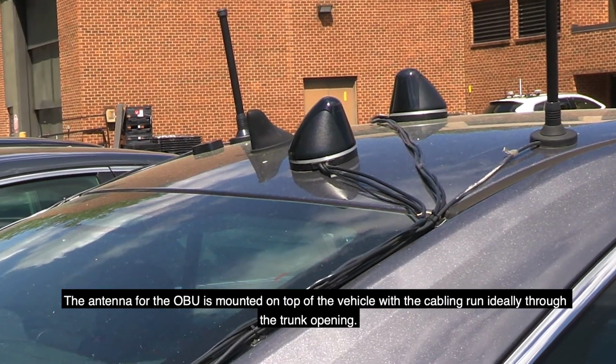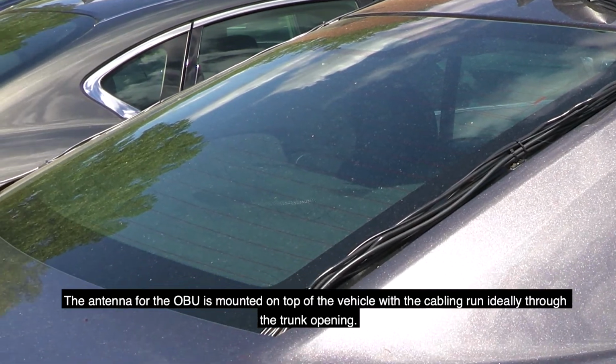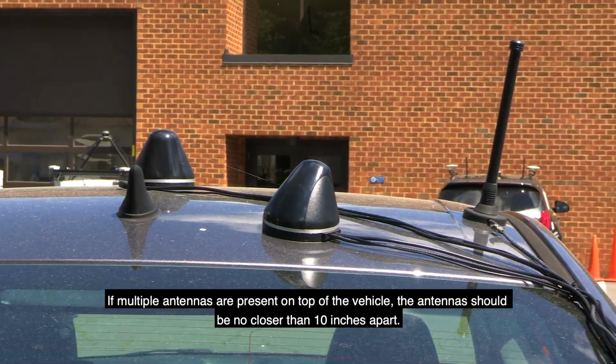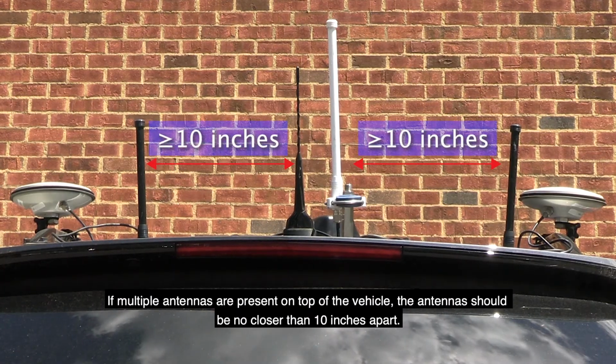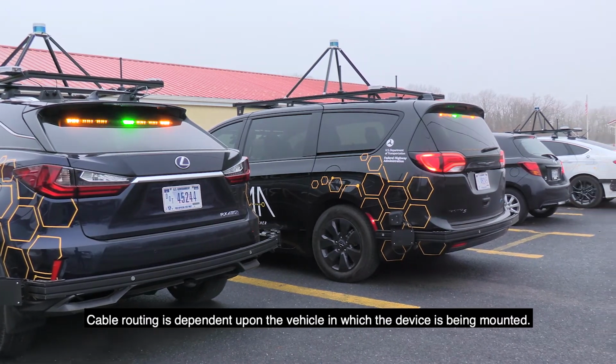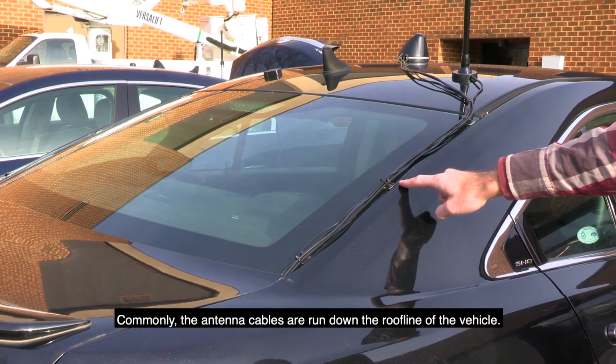The antenna for the OBU is mounted on top of the vehicle with the cabling run ideally through the trunk opening. If multiple antennas are present on top of the vehicle, the antennas should be no closer than 10 inches apart. Cable routing is dependent upon the vehicle in which the device is being mounted. Commonly, the antenna cables are run down the roof line of the vehicle.